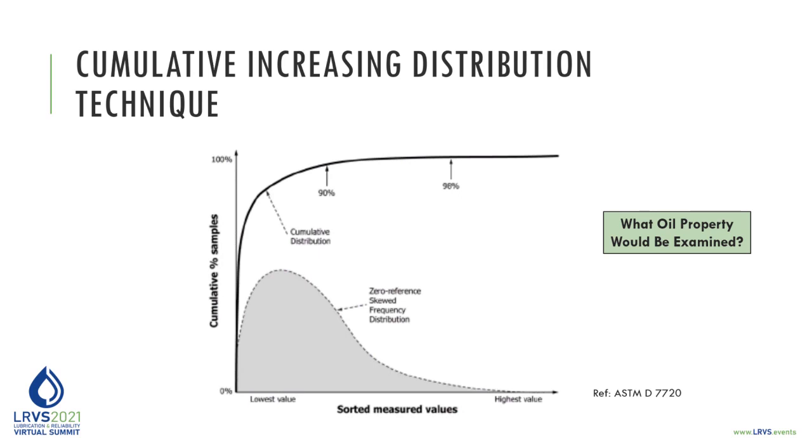And here's an example of initial measured value are often low, often zero, and then increases as condition progresses. This particular scenario, well, we see this with acid number, oxidation, and even relative permittivity for examples of dielectric constant and so forth. The equipment applications where data follows what's considered a sawtooth trend, sharply dropping to near zero after each oil change and then increasing over time.